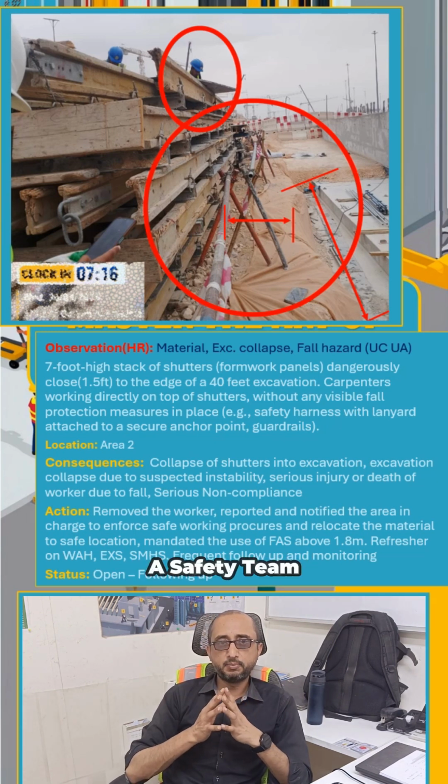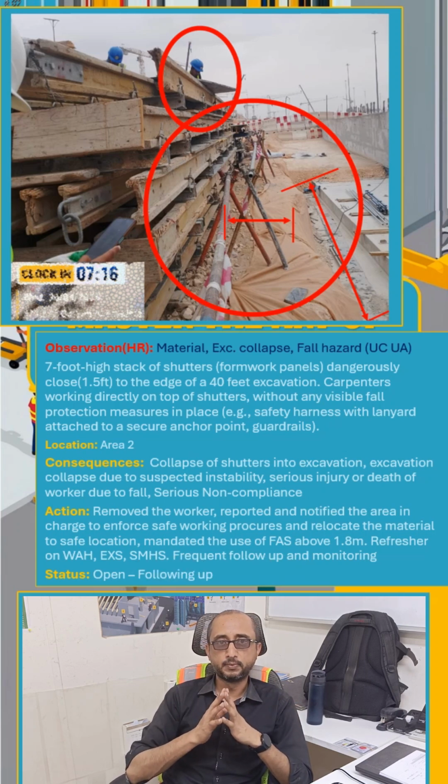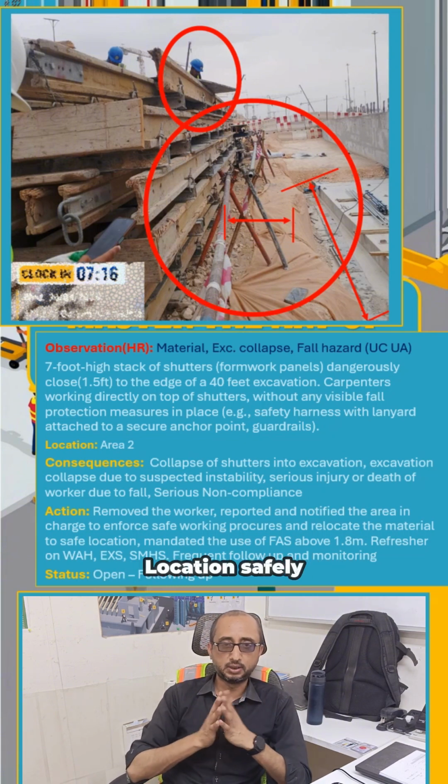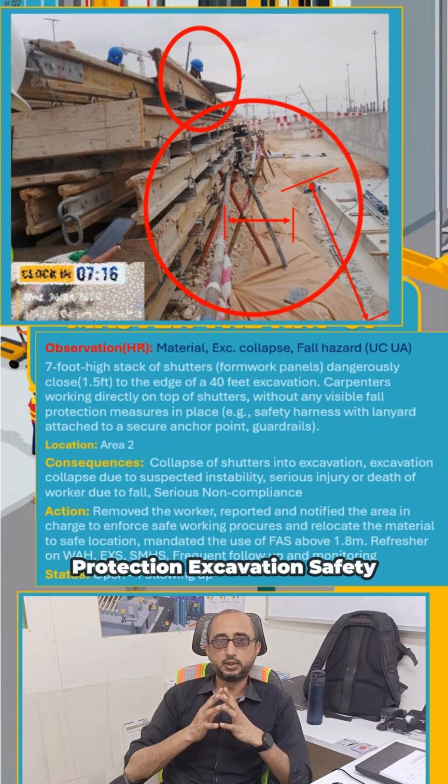Action taken: the safety team immediately removed the worker from the top, reported the issue, and notified the area in charge to restrict any access to the specific location, and then implement the safe work procedures effectively. Relocate the shutters to a safe location safely, and mandate the use of a full body harness for any work above 1.8 meters. For the teams involved, trainings were recommended on work at height and fall protection, excavation safety, and safe work method statement.